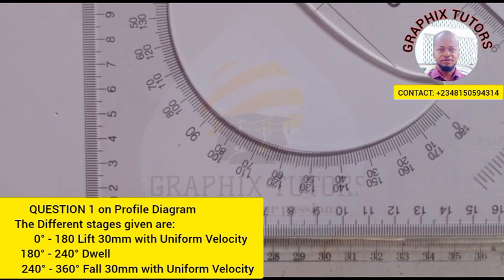The first thing you do with all this motion, the movement we have in a circular, is the displacement of the follower. From 0 to 180 degrees is rise, or lifting, from 180 to 240 is dwelling, and from 240 to 360 is falling.